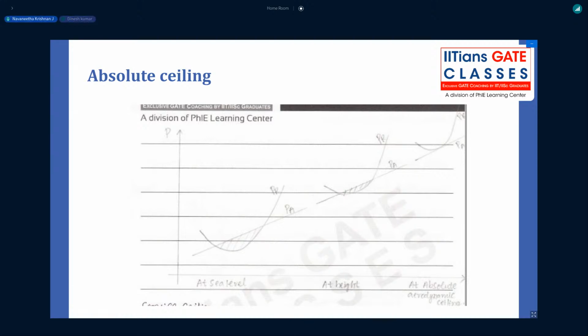No, angle of attack is different and climb is different. Angle of attack is the angle between flight path and your chord line. Angle of attack changing doesn't mean that you are changing your climb.